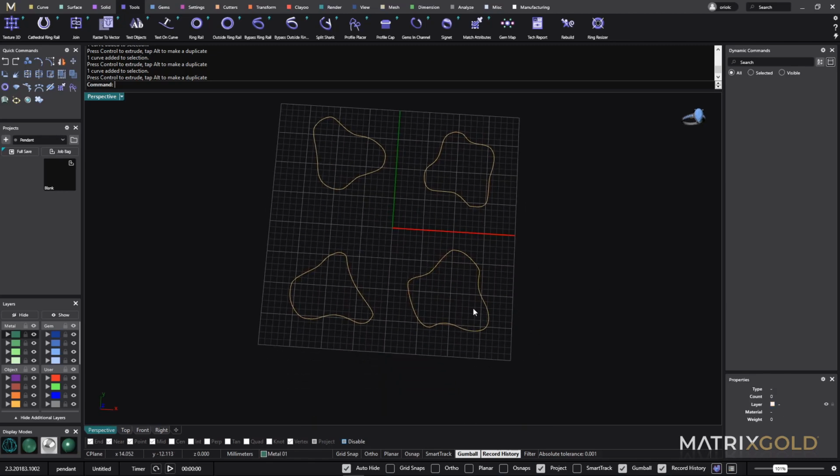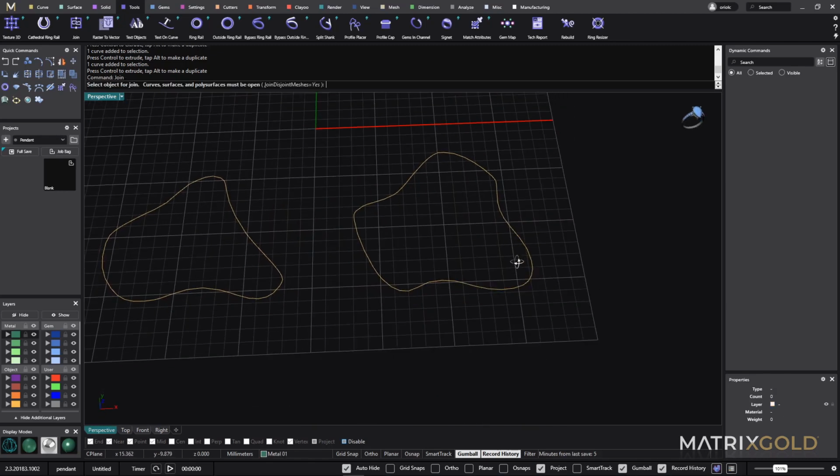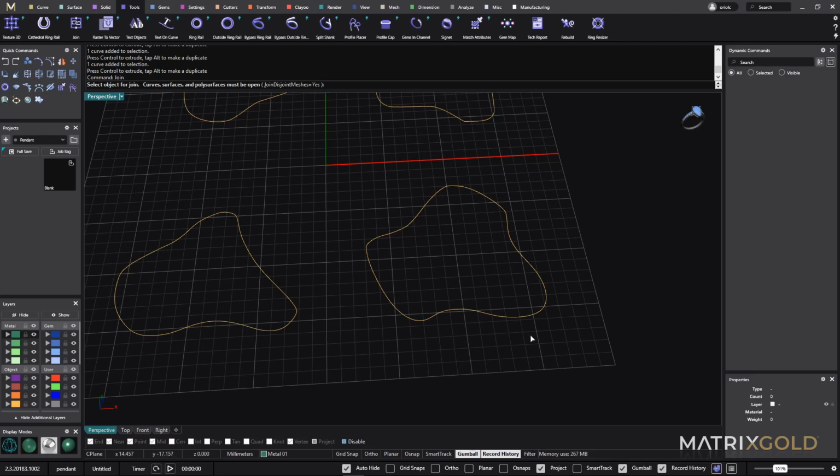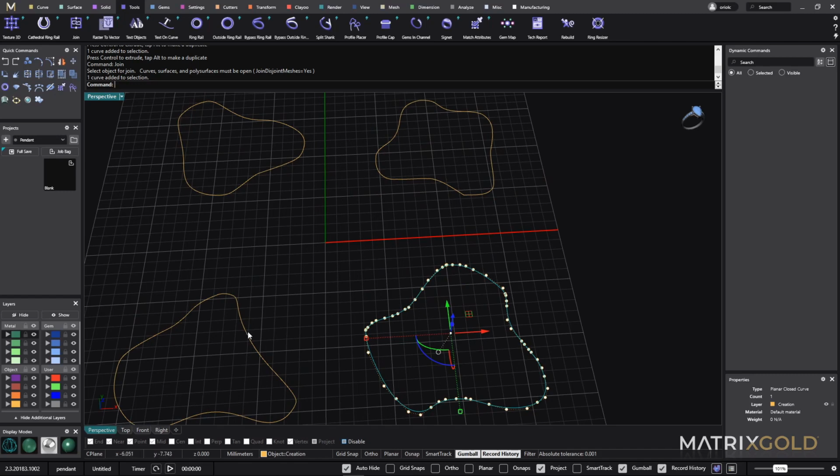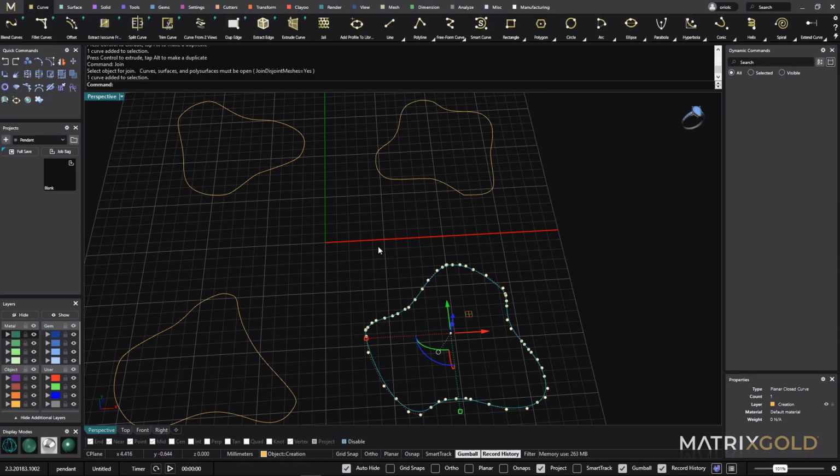All right. Let's see. The first thing that we need to do is just, I will work with one. Okay, so what I'm trying to do here is make a tool which will allow me, by just changing one curve, to get the result from all these different shapes. Let me show you how to do that. I will go first to extrude this curve. Keep in mind that now the points that we get is the ones that we took from the raster to vector.